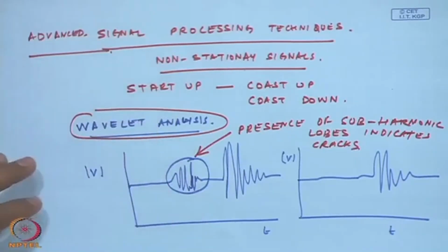Earlier, people were never monitoring cracks through such vibration monitoring. They only did an NDT test either through ultrasonics or dye penetrant to locate cracks. But nowadays, with the improvement and the understanding of the science, and these algorithms having come up, people can find out the occurrence of such cracks in such systems.